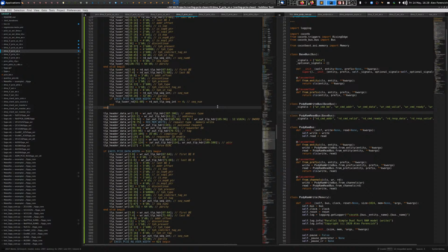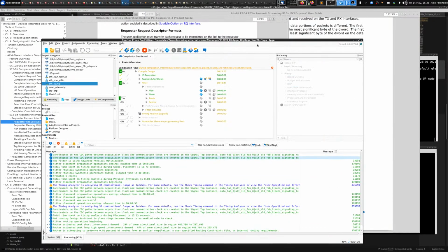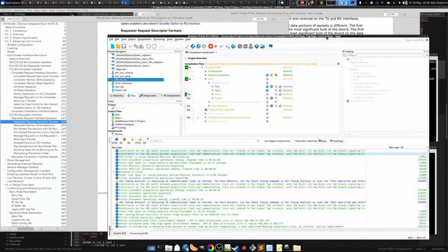So in principle, not that big of a deal, but 1,000 registers is 1,000 registers. But the flip side, if it does make the code more generic and more portable, then it's a significant advantage. One of the main advantages of this particular setup is I can use the same PCI Express DMA core logic across all of the different targets, and I don't need to make a DMA module for each FPGA. That was how I was originally planning on doing it, but after I came up with this idea, I'm definitely not going to do that, because that's just going to create a huge amount of annoyance.